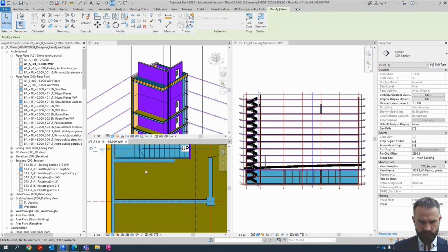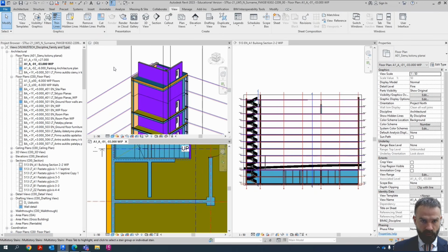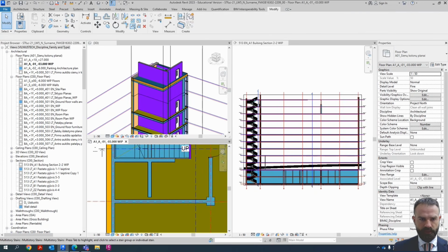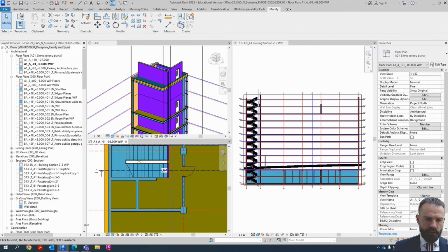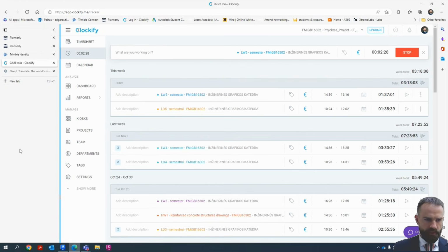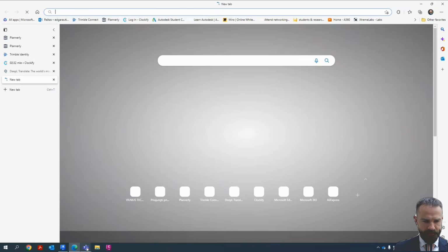So for the elevator, I will copy this wall and make a small room here. Delete. Use modify, extend, and extend the walls here. So let's say this room will be for my elevator. Regarding elevators, I highly recommend to check out an elevator tool.